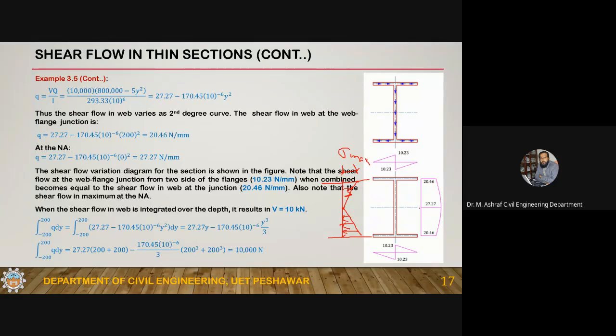But if you are making it thinner, what will happen? Stresses will get increased. And if the stresses are increased, then it may reach the strength of the material, and that will cause a failure. So if you want to strengthen a beam in shear, then strengthen its web. Strengthen means increase its size, increase its thickness.